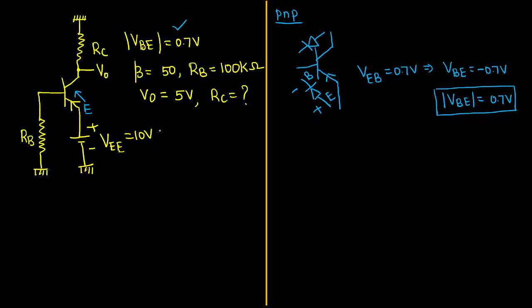It is a PNP transistor. That is the first thing we determined. Next, here we are going to measure the voltage from emitter to collector, VEC. This is going to be plus, this is going to be minus. Opposite direction. Because current is driving into the transistor from the emitter, whereas from the base the current is going outside. For the collector also the current IC is going outside, like this. Yes, sir. Now, this is the base resistance. Current entering point plus, leaving point is minus.